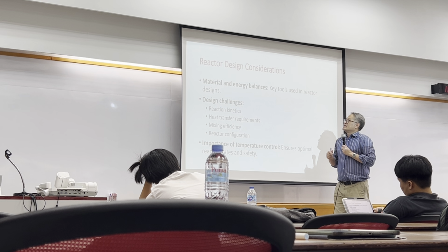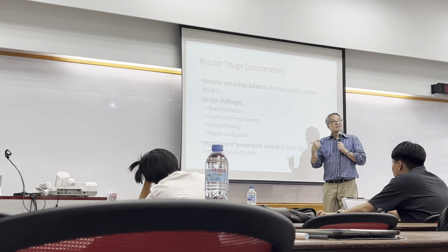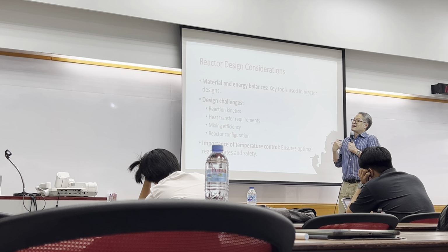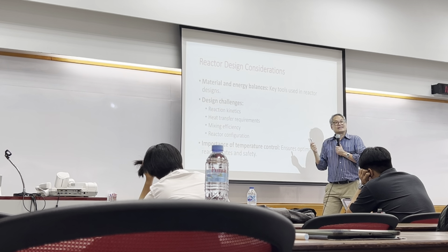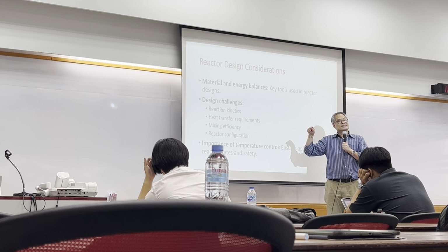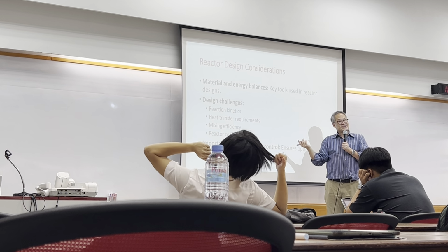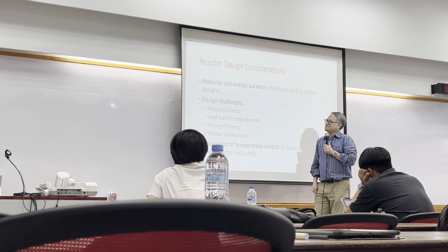The design challenge is the kinetics of the reaction. Depending on the rate expression for each reaction, you have to design the reactor based on that. Heat transfer requirement: you're going to run it as adiabatic. You've heard adiabatic before, right? Q dot equal to 0. Or you're going to do isothermal, where we keep the temperature constant.